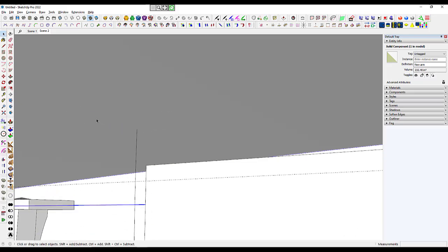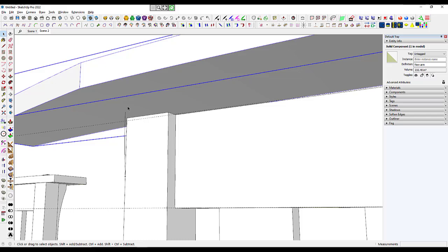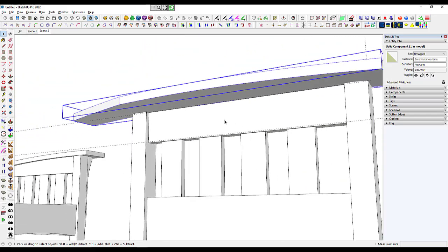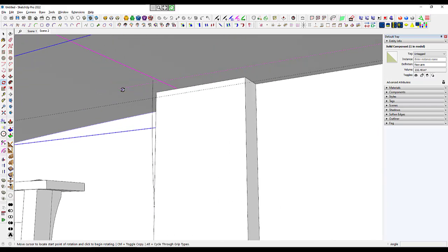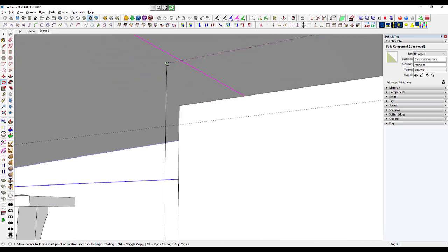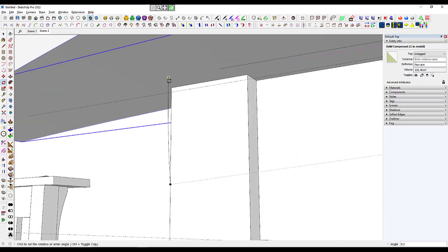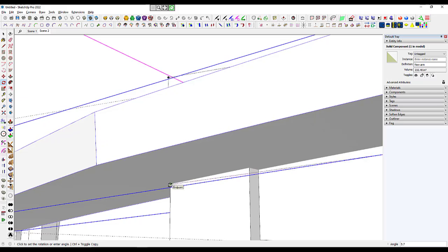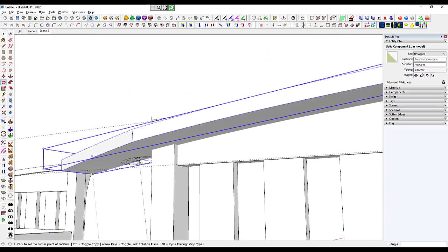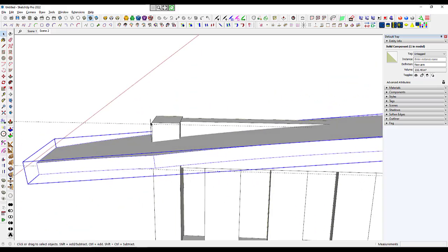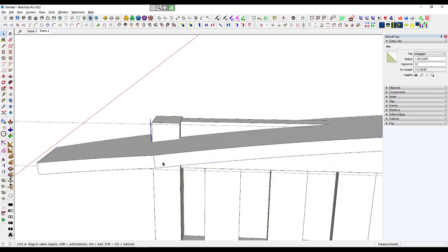And then, with that armrest selected, I'll switch to the rotate tool. I'm going to press the right cursor key to lock that in the desired orientation. And now from that guide point as the center of my rotation, I can come from this end point, the top end point of that arc, down to there. And now that's in the right location. And I'm finished with the arc.